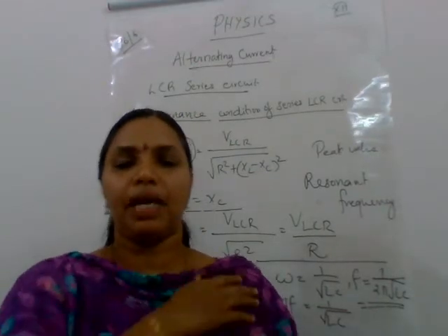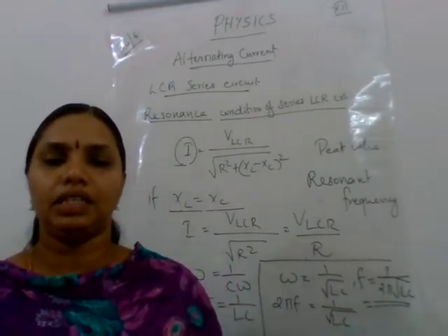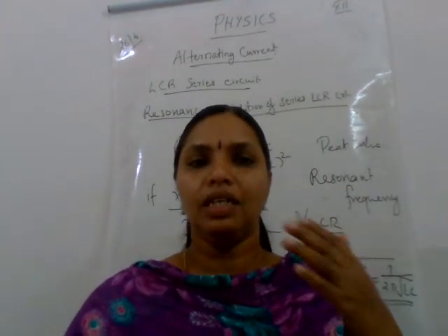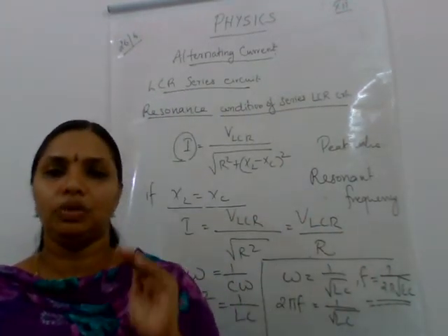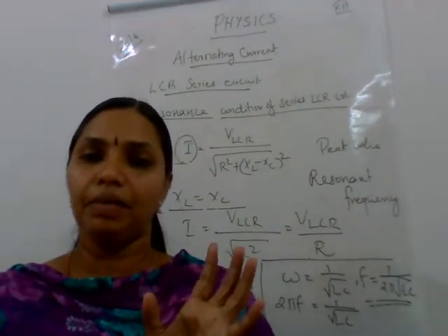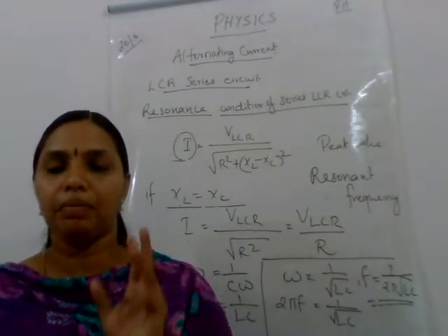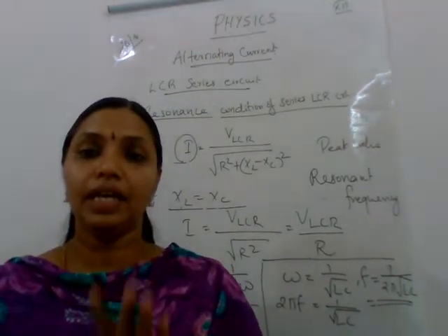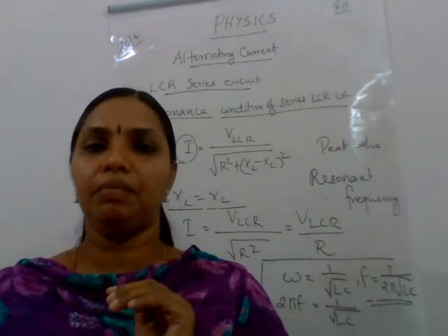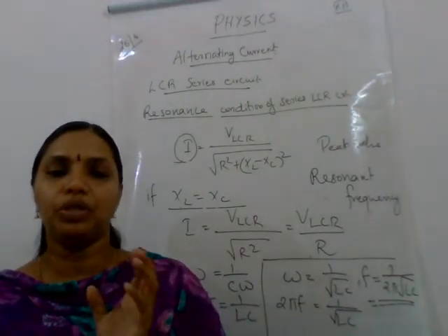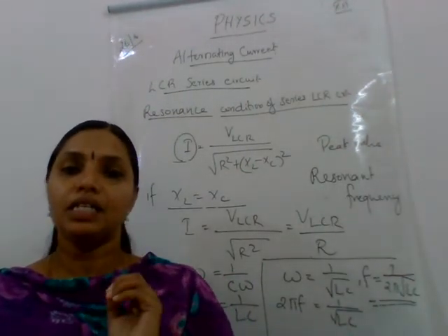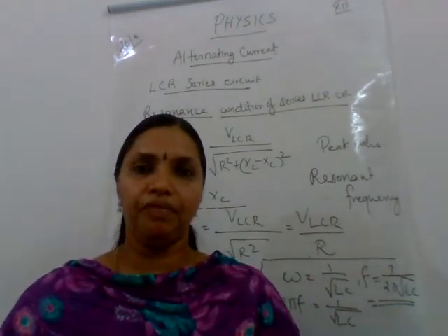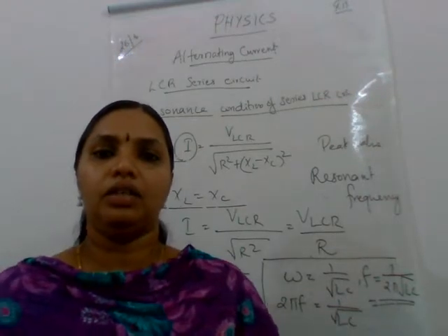At resonance, the impedance is minimum and the current is maximum, and the circuit behaves as a resistive circuit. So the voltage and current will be in the same phase.